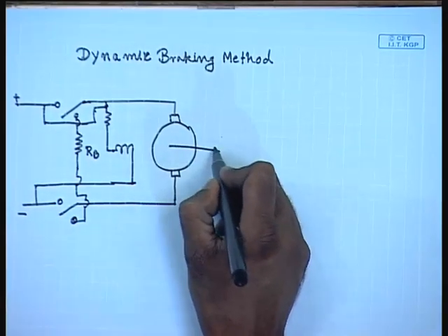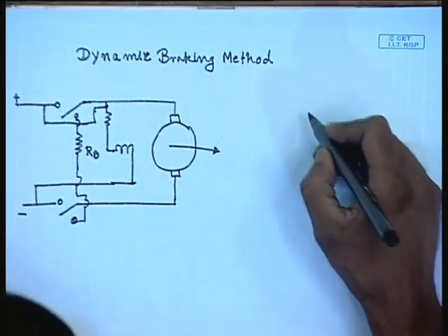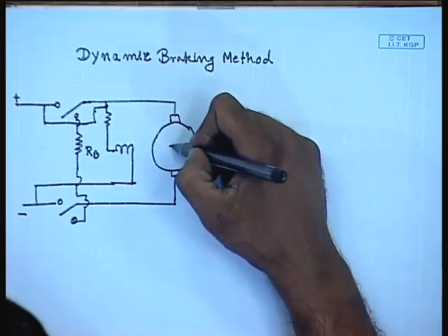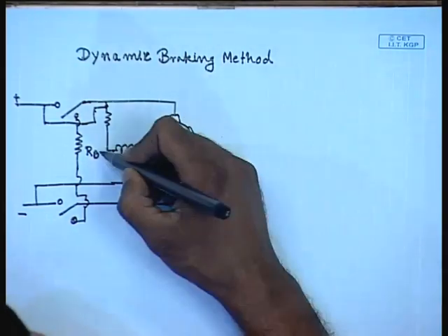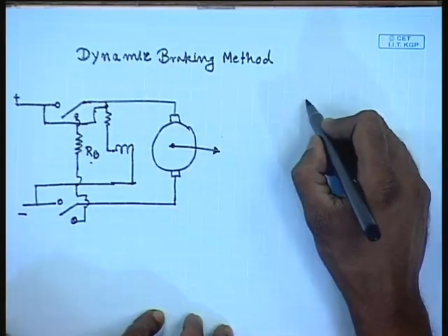So again the motor acts as a generator, and the kinetic energy stored in the motor and load system is dissipated in this resistance.